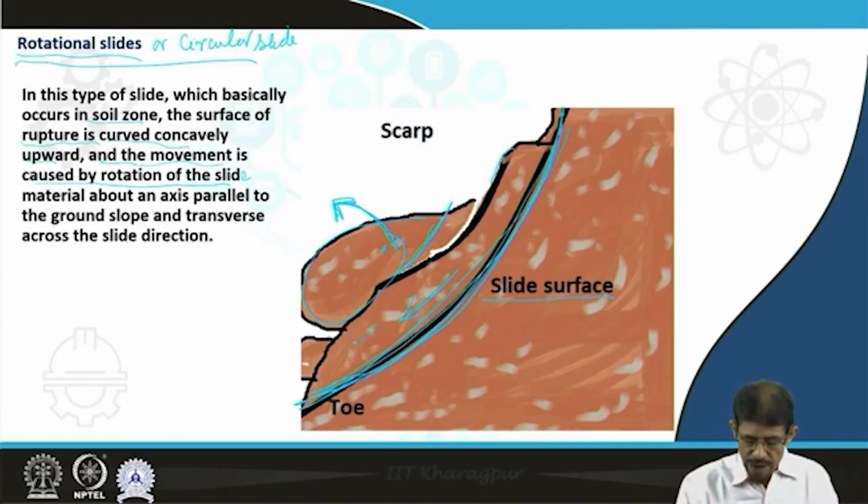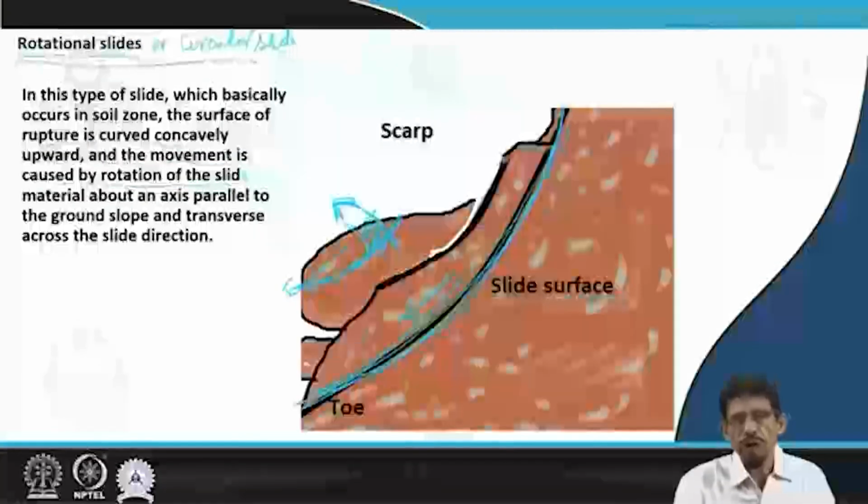Sometimes the slid mass starts showing development of another secondary slide surface or potential rupture zone. So the material lying above this secondary surface starts moving as a secondary slide within the slid mass. Maybe there is development of a new slide surface, so this material starts sliding. This type of phenomenon we generally encounter in soil dumps, mine waste dumps, domestic waste dumps, etc., particularly in the rainy season when this mass is under saturation, and after getting saturated this mass becomes heavier and prone to showing varieties of slides belonging to the circular slide of different dimensions.